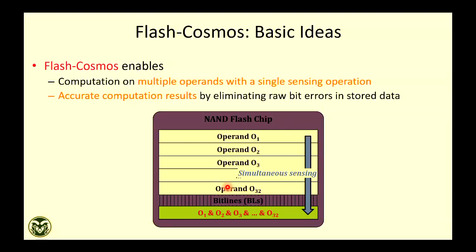Suppose this is storing 1, this is storing 1, this is storing 1. Then if you put VREF here, say 0 volt or 1 volt, this is the minimum reference. Erase voltage is negative. An erased cell has a low threshold voltage, so you don't need pass.